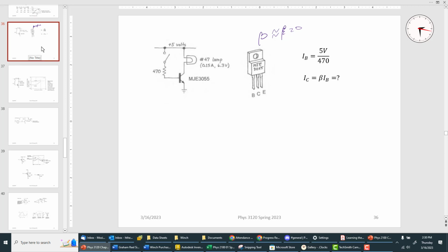So you need to take the leads and grip them with your needle nose and twist them 90 degrees, because you're going to put them in across rows, and then they're rectangle shaped, and the contacts are actually rectangles. But the problem is they're oriented the wrong way. So you have to twist the leads 90 degrees. And if you're not sure, let me come and help you, because you'll damage the breadboard if you don't.